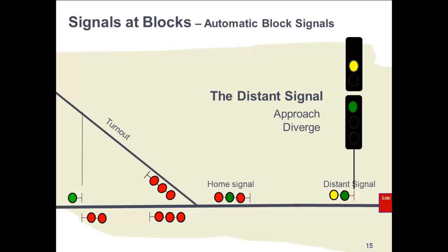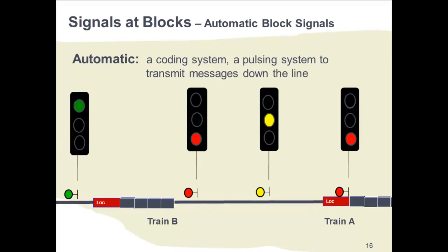And on the previous slide, we noted that there can be variations in the meanings of the signal aspects. We said that red in ABS means stop and proceed at the restricted speed. Does the red signal at the interlocking home signal mean something different? Yes, it does. A red signal at a home signal means stop and do not move. Stop and stay. Well, let's move on to talk about the electrical functions that create the automatic signal.